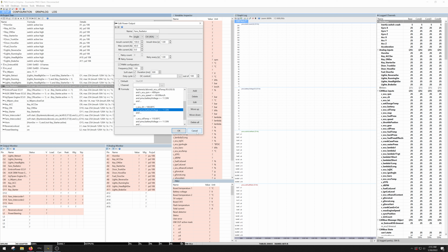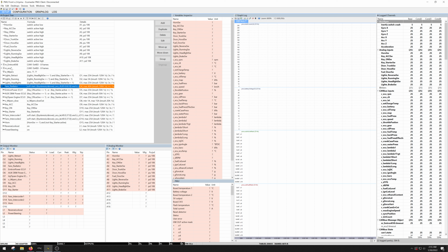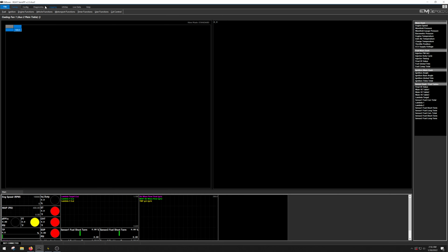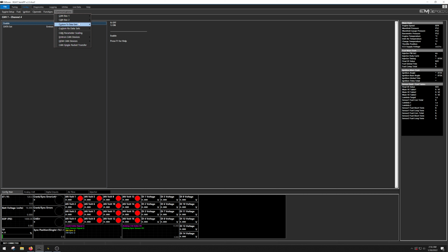So the main thing here is I will be importing all of these frames from various channels from the ECU, whether it's engine speed or G-force, any imaginable data set off of these custom communications that I'm creating. So let me show you guys what I did for custom creation for a transmission data set, which is the ECU TX transmitting to the PMU.